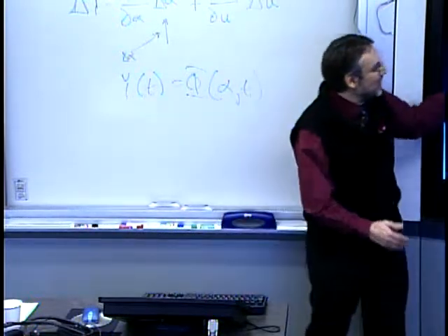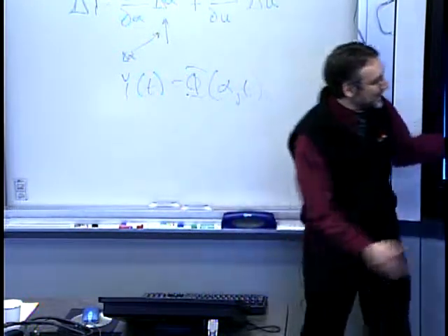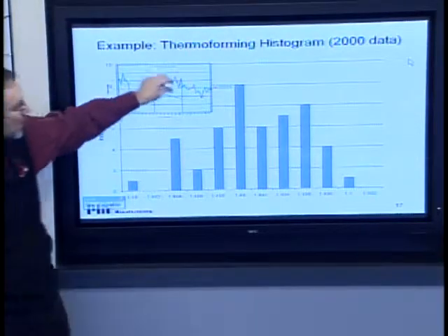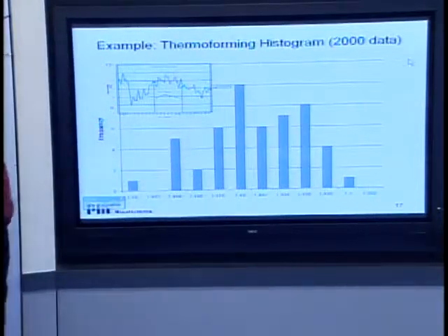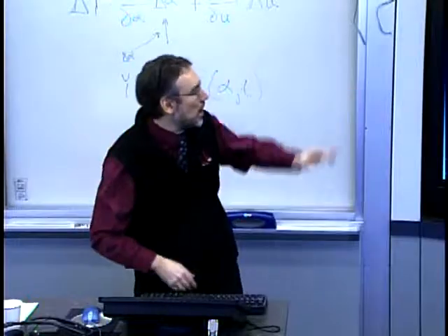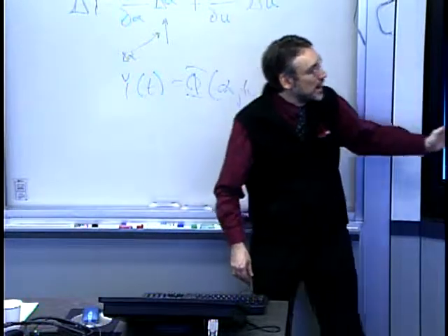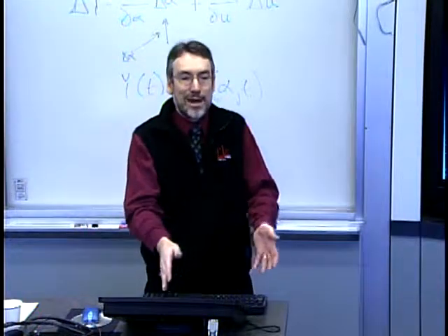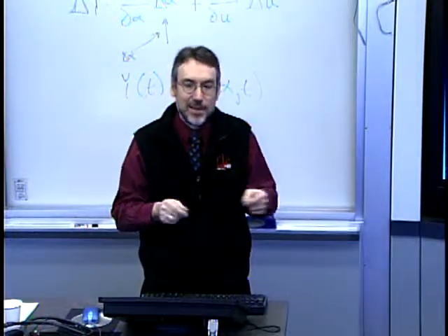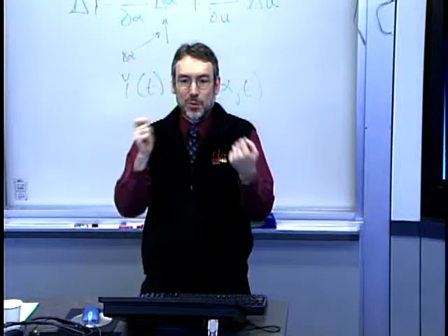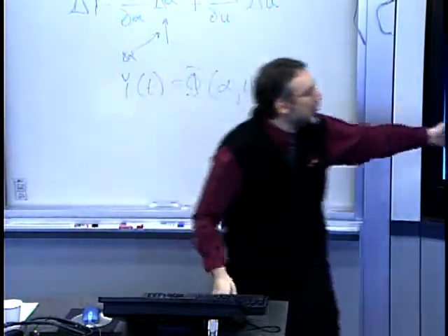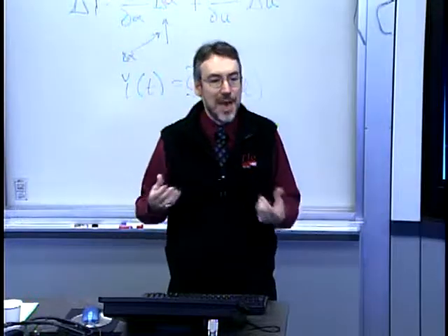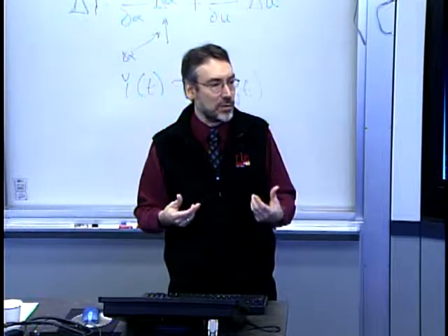And then if I were able to get that out of my process, then I might have a random component that doesn't have that deterministic or systematic component. And it might have a distribution, but it might be much, much tighter. Right? So an important point here is purely empirical data may look random, but it may have embedded in it, if you were to deconvolve all of the sources of variation, this big normal distribution may have mixed into it lots of different systematic components as well as underlying natural variation.